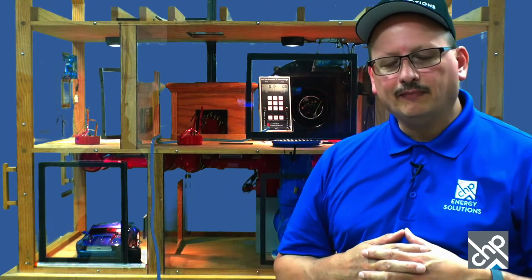If it goes negative, then we know we've got more supply leaks. If it goes positive, then we know we've got more return leaks. But there may be other times when you get a 0. So if you get a 0, it basically could be one of 3 things. It could be that there's no leaks, which is usually not the case. I mean, newer houses now, they're getting better at tightening ducts, so that might be on a newer house.